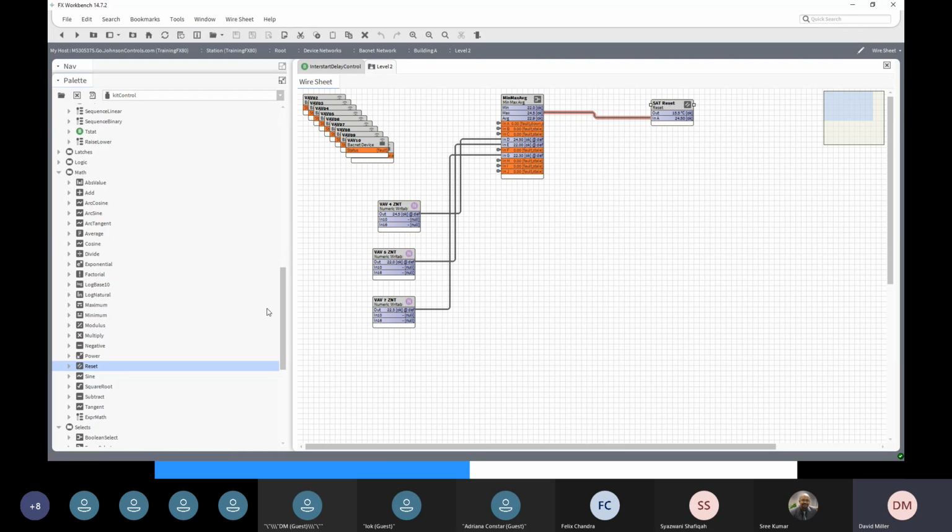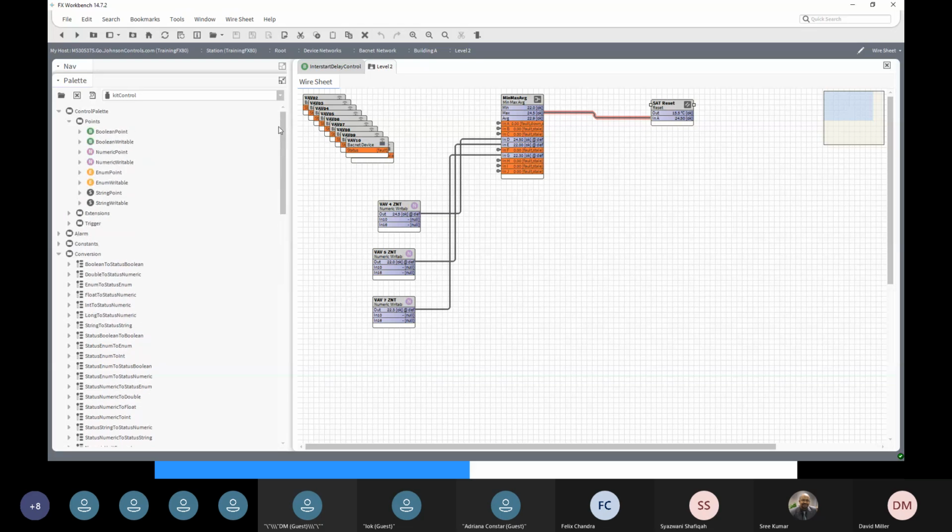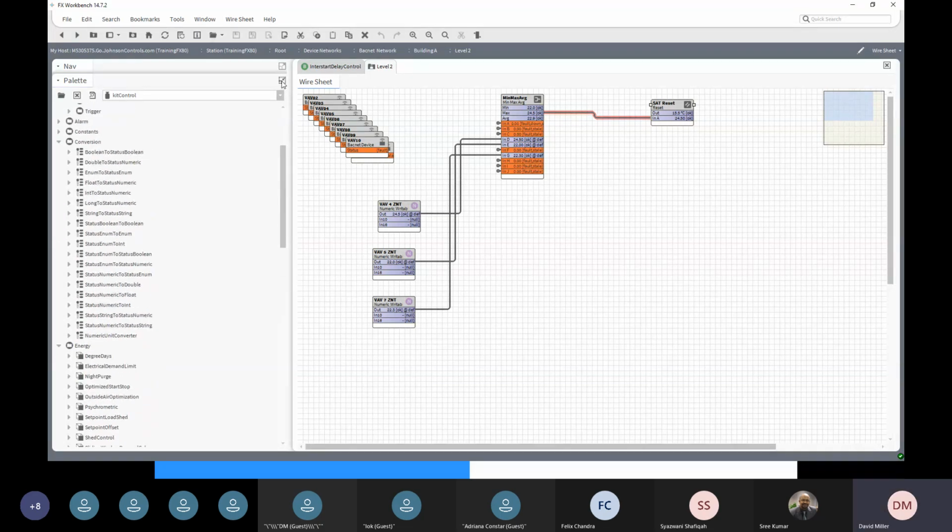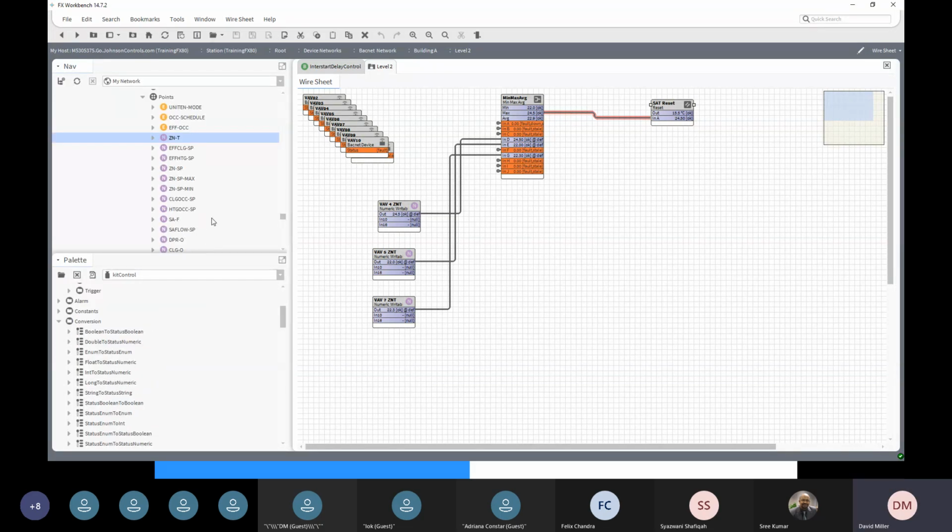Now, in my air handling unit, so this is all, so minimize this back to there. This is all on my VAVs on level 2. There's my air handling unit on level 2. He's got points and he's got a discharge air temperature set point somewhere. Discharge air temperature set point, which I want to be 15.5 degrees.